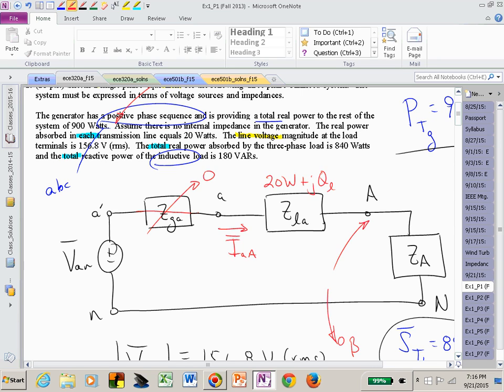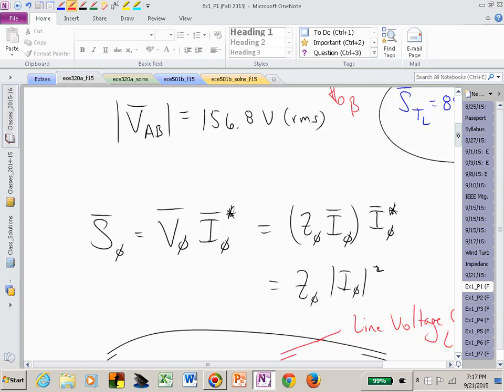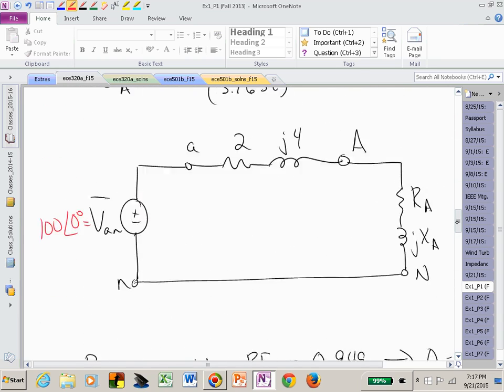And this again gets back to that question, where do I put my angle on the generator? You just have to keep track of it as you're working through the problem, but at the end you could arbitrarily say it really doesn't matter in this single phase equivalent. All I need to know is a particular angle at this generator, and that could be 0.